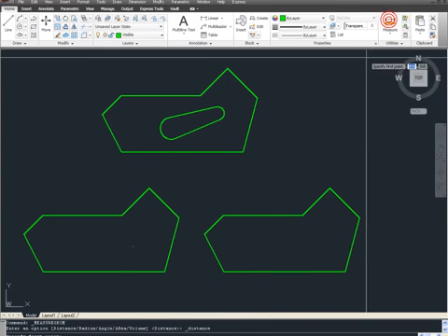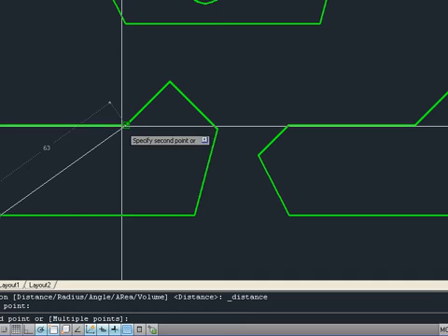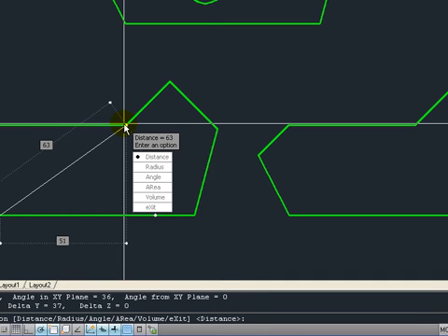I'll click on this tool and measure the distance from this point to this point. And notice that this time AutoCAD told me exactly what that distance is. It's 63 units. But it also tells me that the angle in the XY plane is 36 degrees. In other words, if you're looking at this white diagonal line that appears on the screen, the angle between that line and the original line that we measured, that angle is 36 degrees.